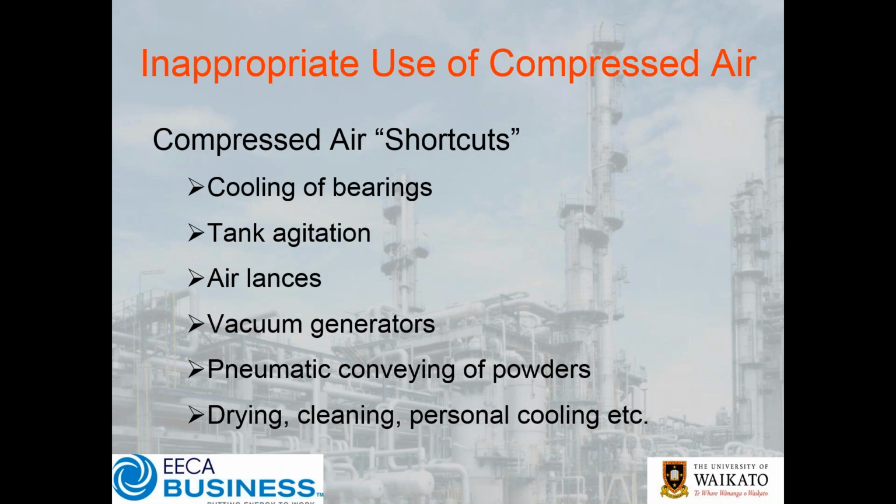Now you might argue that if you've got a bearing that's really, really expensive and you can't shut down to replace it, as a short-term interim measure, you might pump some compressed air in to cool it. Now the danger, of course, with that is what starts out as a short-term filler or stopgap measure to keep the plant running very quickly over time evolves into business as usual, and before you know it, you need another air compressor. So it's really important, happy to acknowledge there are times when you might need to do these things as an interim stopgap, but it's very, very important that these things don't become part of our business culture or business as usual.